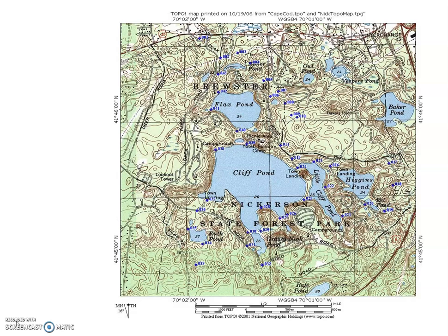And you can see, if you look at 0.8, the radius of the circle that you'll need to draw to mark the recharge area is 0.58 miles, which we can round off to 0.6 miles. Now, if the instructions had said calculate the recharge area in millions of gallons per day for 0.4, you would have read across to the radius of the circle and seen that the equivalent was 0.4 miles.